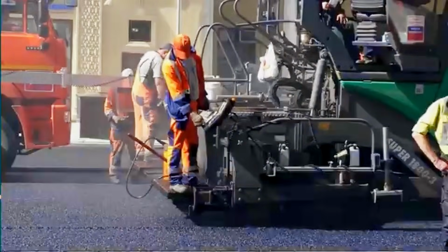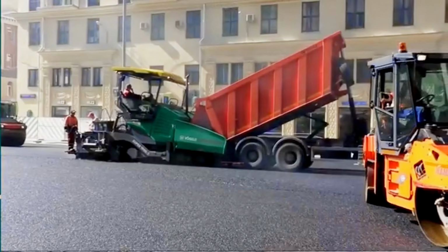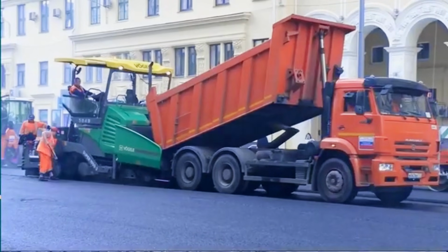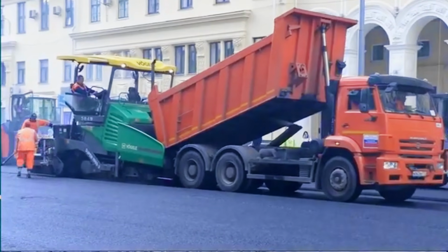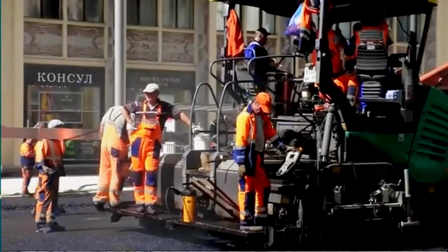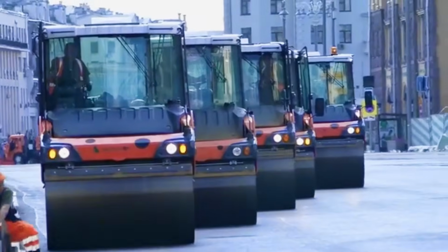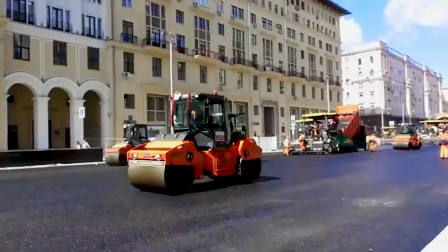Automatic sensors on the paver shall ensure proper line, grade, and level. These sensors are guided by string lines fixed by surveyors using stakes and arms on both sides, typically at 0.5 meters from the edge. Compaction shall begin immediately after laying the mix.